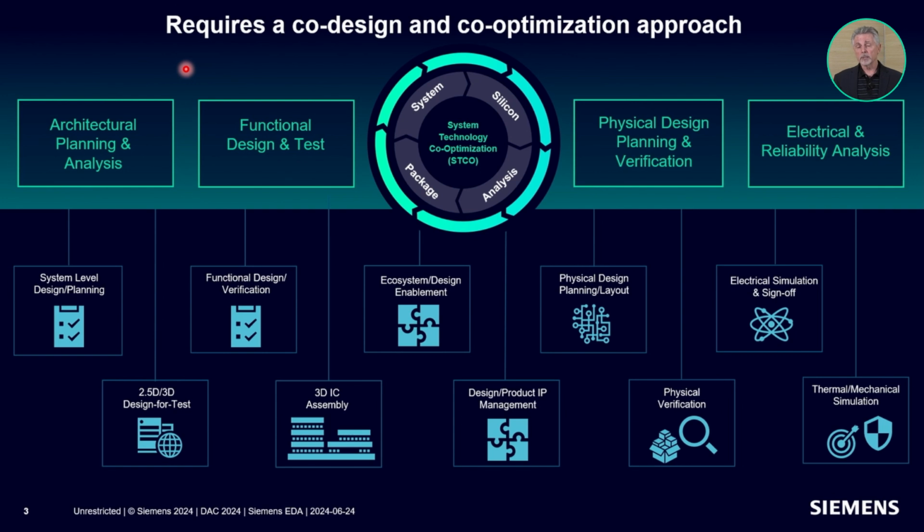This includes things like signal integrity analysis. These are for the high-speed internal interfaces, the die-to-die interfaces, as well as the external interfaces, SerDes, DDR, and such. And thermal and stress analysis is also important. So really there are 5 key areas: the physical design, we have electrical analysis, we have reliability analysis, and then test. That starts up front in the planning, but also as you deliver your parts off for manufacturing, we have to generate test vectors, both for the individual chiplets as well as the complete system in package.